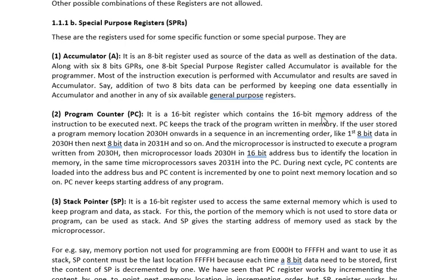So this is an easy way. We can represent any binary data in hexadecimal in a very easy way, and without any confusion. That means 8-bit data can be represented using 2 hexadecimal digits, and it will vary from 00H to FFH in hexadecimal. F means 1111, another F is 1111. Total 8 bits, 1111 1111, in hexadecimal will be FFH.